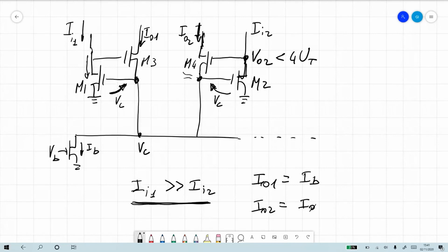That's why it's called a winner-take-all circuit, because the one that receives the input which is sufficiently larger than all the other inputs takes all of the bias current, and all the others are switched off. So if you look at current mode, the output is going to be IB for the winner and 0 or I0 for the losers. And if all the inputs are perfectly identical, then the output is just IB divided by the number of taps. In our case it's 2, so it's IB half. But if you had 4, 5, 6, 10 nodes, it would be divided by 10 or so.